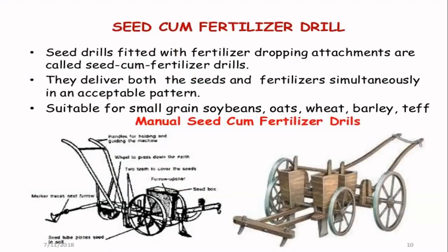You see the ancient manual seeding by man. The conventional seed drill in the earlier stage was mostly developed in European countries. But in Sri Lanka, a lot of manual labor is used. A seed drill fitted with a fertilizer dropping attachment is called a seed cum fertilizer drill. I told you, they deliver both seeds and fertilizer simultaneously in an acceptable pattern, suitable for small grains, soybean, oats, wheat, barley, and turf.